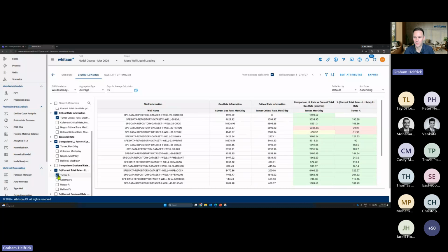One thing I've seen people use this for is if their results are looking weird or blank, that can be a way to flag that there might be something missing in the wellbore. This is just a bit of a QC thing. If there's something very weird or just blank, it means there's probably something missing in the wellbore description to calculate the bottom hole pressures.